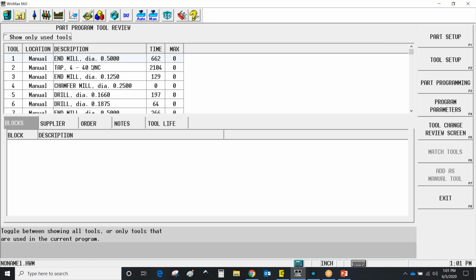And it's the same tool library for both NC or conversational. That was one of the other things without the Tool Material Library. If you created a tool in conversational, say tool number one was a 1/2-inch end mill, then you brought up an NC program, tool number one could be a 3-inch face mill. So with the library, they do share the same tools.